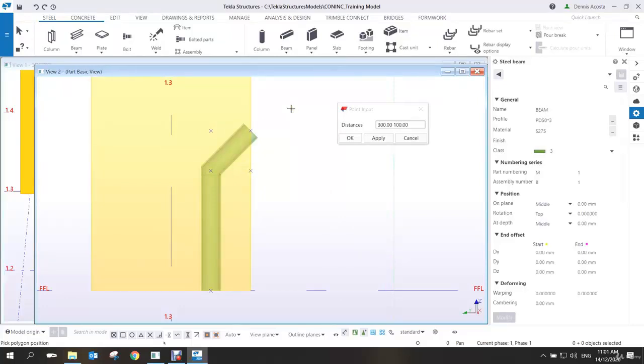But you need to make a view like this, make a plain view first. If you're not well versed in the 3D, in creation in the 3D, then you can always go back to the 2D view, Control P. Control P is a plan view. Because this one I create a separate view.